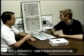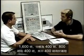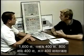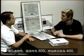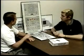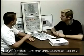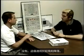Another one we have out there is the minimum desired landing fuel, which is 1,600 pounds, broken down to 400, 800, and 400: 400 for the landing or at touchdown, 800 for the go around, and 400 for the fuel gauge error. That 3,300 fuel imbalance, is that all phases of flight? No, that's only for takeoff and landing.